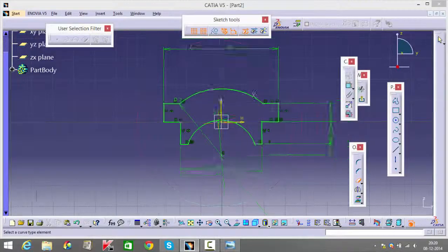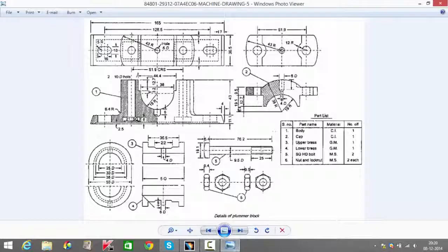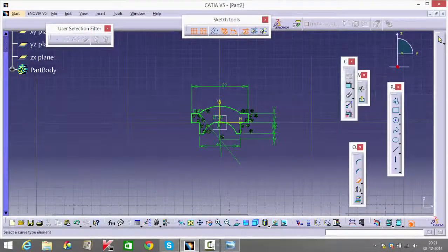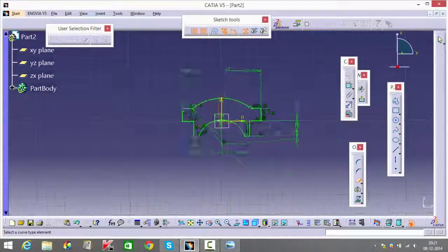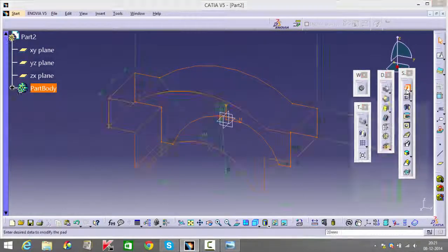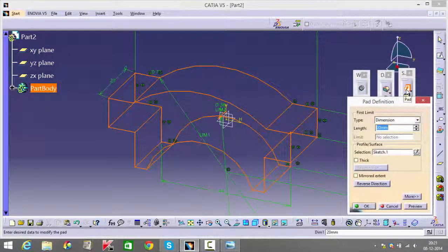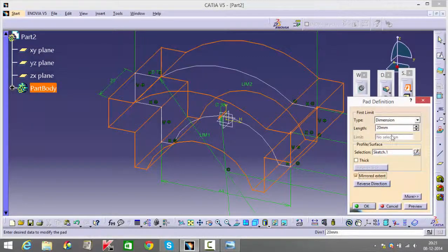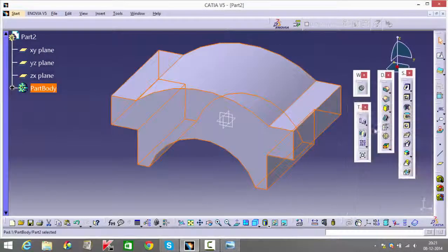Yes. So this is what we want. This is your figure basically. This half from here, this whole thing, again only till here, and then this top portion. So this is your part 2, and it won't take too much time. All you need to do is think, or just apply yourself. I'm going to pad this. I like keeping my planes in the center, so I always mirror extend my figures, and this is going to be 18.